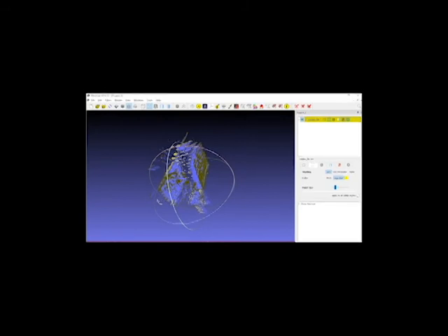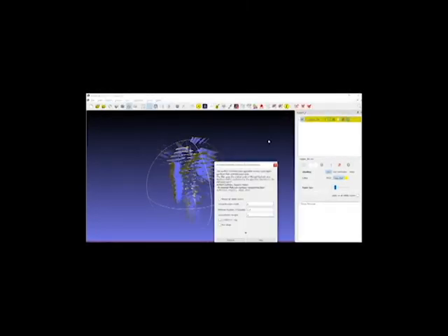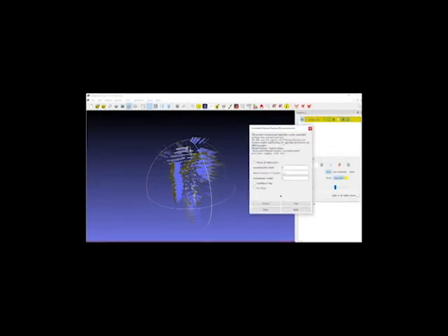They're all pointing away, so that you can just kind of see where the faces are going to form. Next, I want to go to Filters, Remeshing, Simplification, and Reconstruction, Screen Poisson Surface Reconstruction. Again, through trial and error, I found out what works for me, so I hit 3, and I hit this Merge All Visible Layers button, hit Apply,